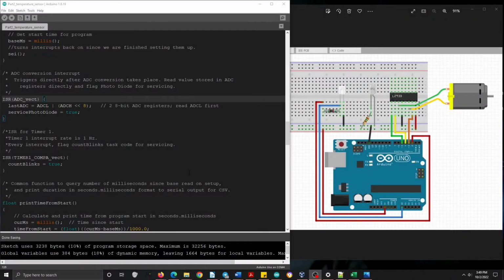Our design involves a round-robin with interrupt approach, using two distinct interrupt service routines, with the main loop checking against two conditional flags corresponding to either ISR action. And if neither is high, it will just continue polling indefinitely.